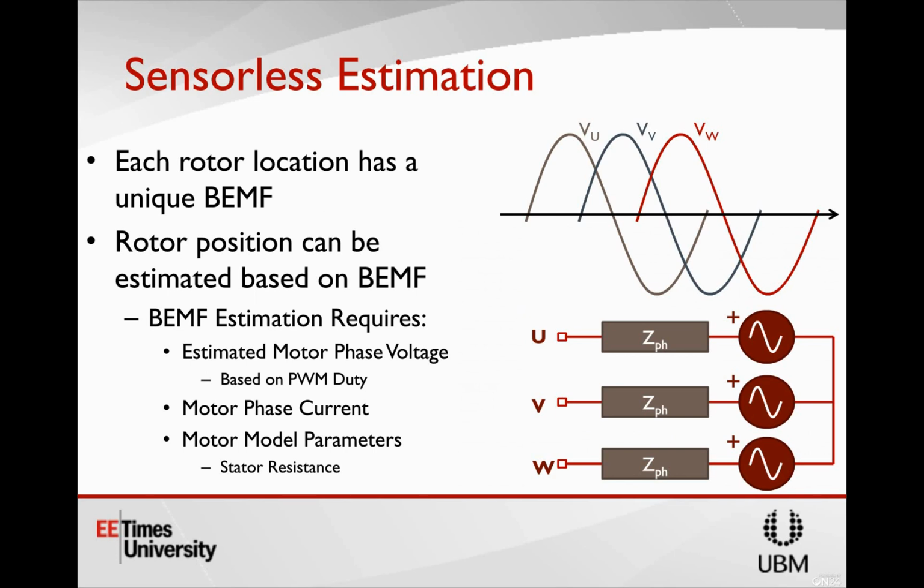So here's one from Tahir. What is normally the startup difference with sensored or sensorless control? Good question. In sensored control, there is never a startup period. The motor immediately begins rotating, because you always know exactly where that motor angle is.